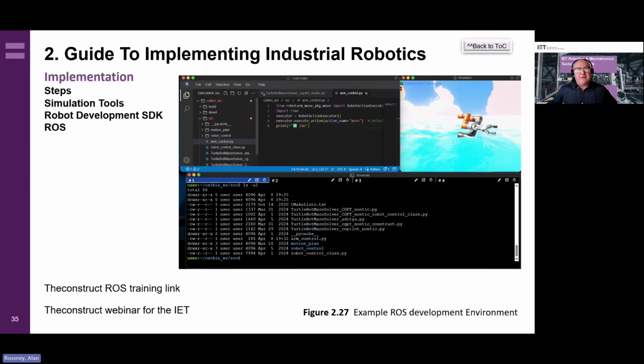So Robot Operating System, I thought I'd just mention that briefly. ROS can be used widely with mobile robots and some fixed arm robots and cobots such as those from Universal. It's a full software development environment, including a terminal. I'll turn on the pointer there again so you can see. So terminal here, and then it also has a software development kit here, which is really just a file explorer, a coding window, and also a utility that checks your code. Then in the top right corner, it has a visualization tool.